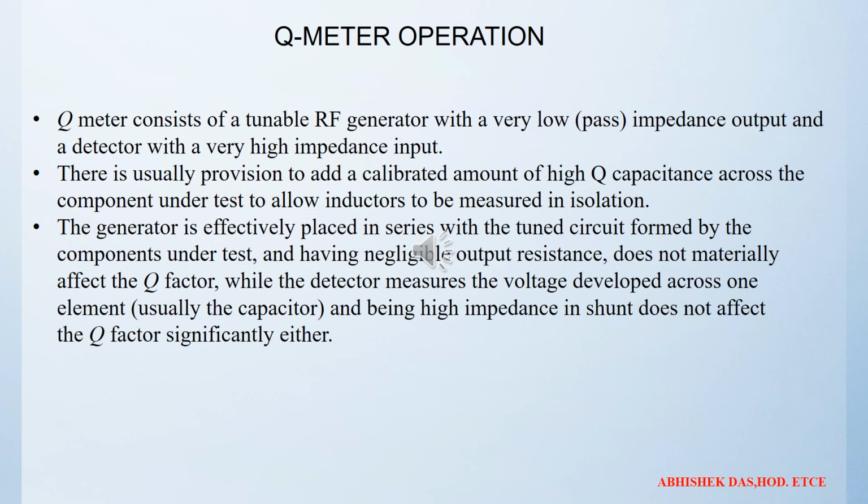A calibrated standard variable capacitor is used for resonating the circuit. An electromagnetic voltmeter or electronic voltmeter is connected across the capacitor. The coil under test is connected to the terminals.